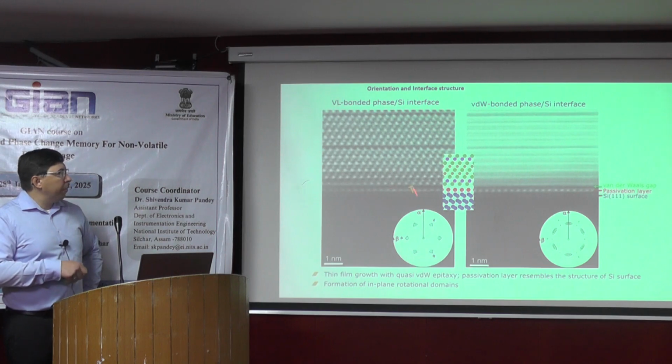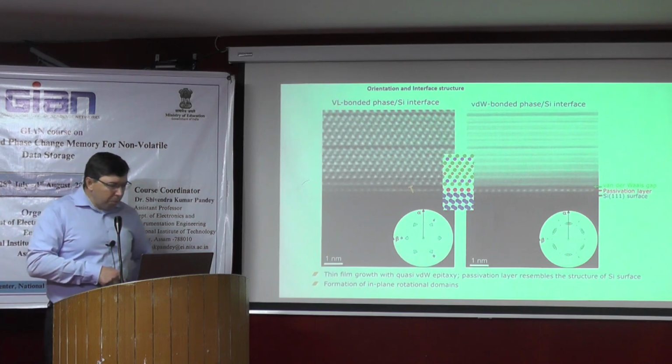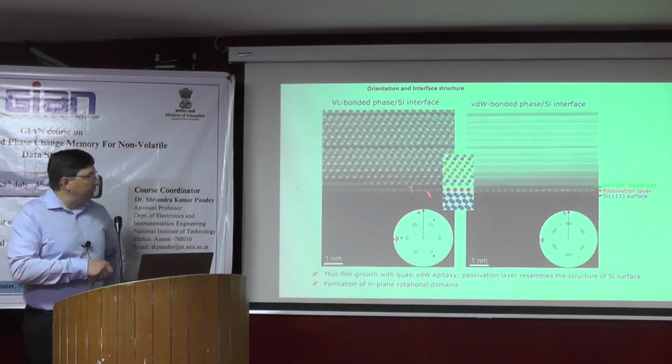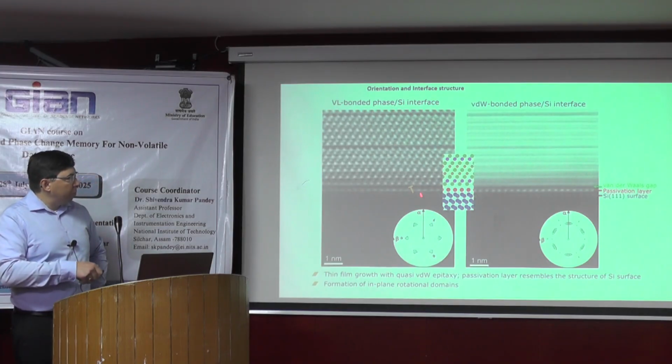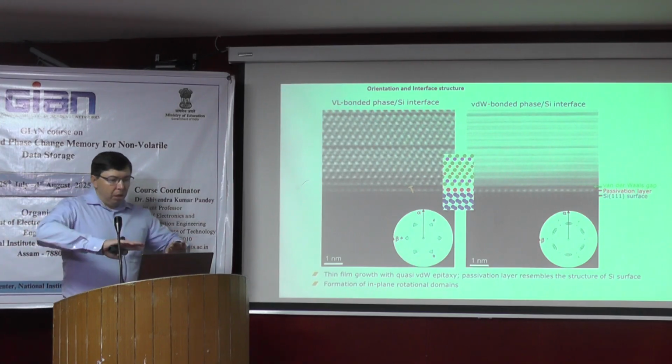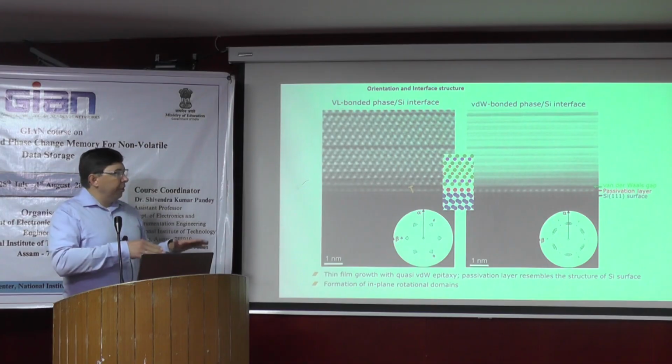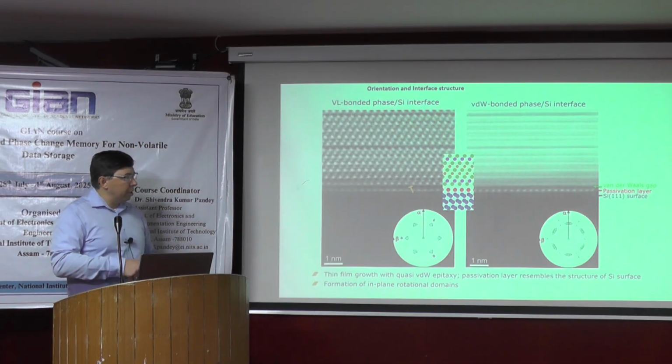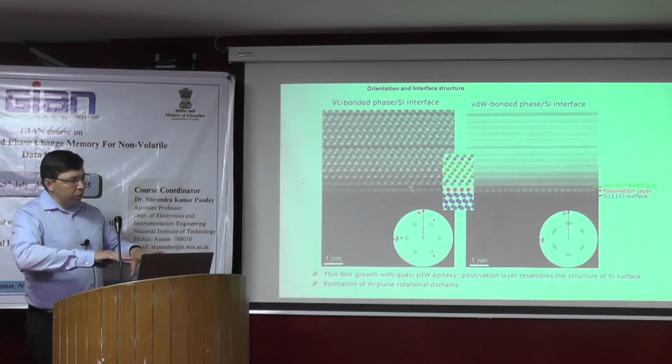First, one mechanism is the formation of dislocations. We also found the formation of some dislocations between the thin film and the layer, but another mechanism is this in-plane rotation. Then the system can be better adjusted to the substrate and reduce the misfit strain.